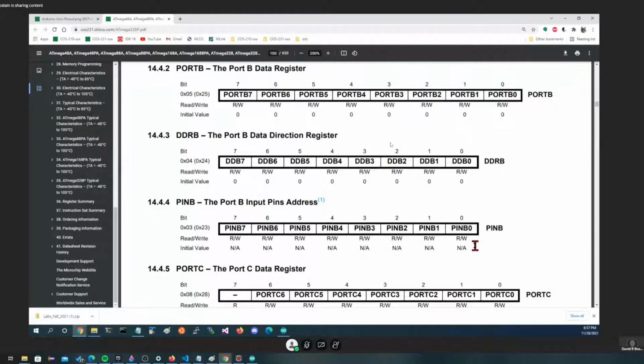Robert? Either nothing or it toggles. Yeah, if you're writing to it, it's going to usually toggle because you're probably not going to write to it otherwise. Good, excellent. Now, the one thing you have to remember with that is you may make it toggle, but if somebody else is driving the pin, then you have to pay attention a little bit on outputs to whether or not it's hooked to a bus or whether or not it is using the same technique that we would have used with an open collector output.